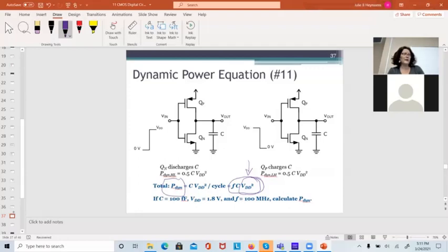Be careful when you put them together. This really happened in the lab this year. We had a board with mixed logic between 3.3 volt parts and 1.2 volt parts, and they weren't paying attention and built the printed circuit board. Every time, they blew it up and fried the 1.2 volt part by putting 3.3 volts to it. You've got to be careful and have level translators between them, and really watch it, because there's a lot of variety out there now.